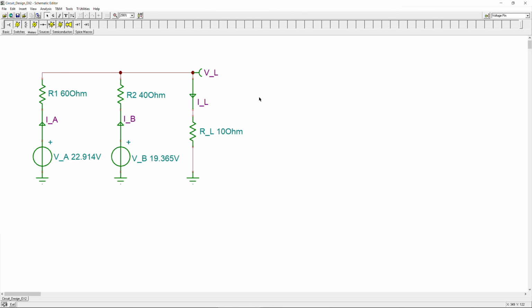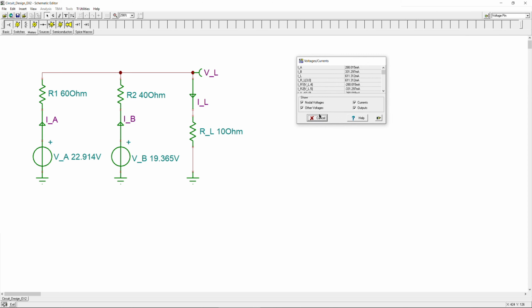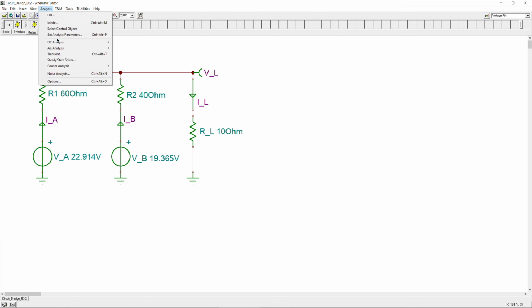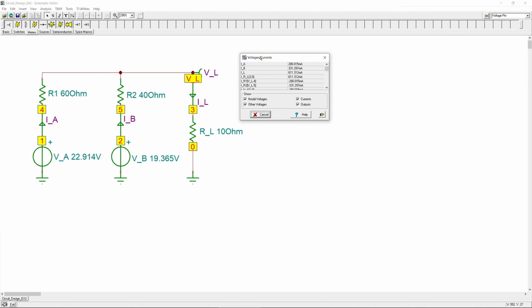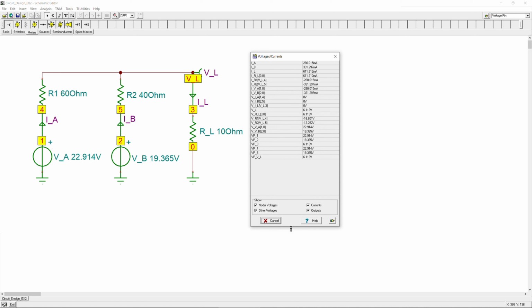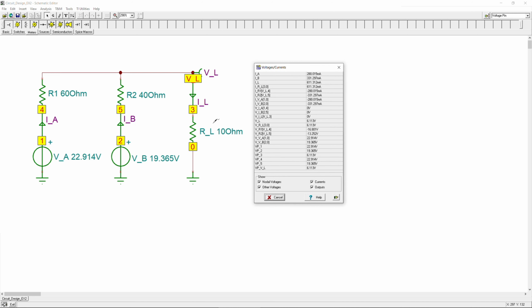Okay, you can also do a lot of other simulation results, but you can also generate the table. Let me also show you that. So how can you do that? Let me again repeat this. You go to analysis again, DC analysis, and then the table of DC results. Click on it. You get it. Now you get a lot of information. Now, again, you can click on a component and see highlighted in red the current and also the voltage.